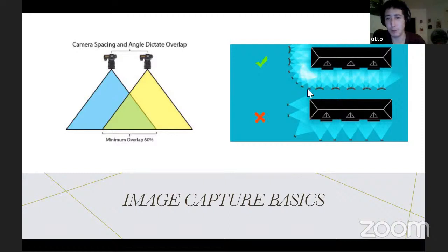And then you want to increase your overlap by basically double over a corner. And that's because corners are where the triangulation between the two faces can come apart. So it's important to have more overlap on your corners so the whole model is captured. Having just one image, as on the bottom here, is likely to cause problems because there aren't enough features detected on either side of the corner for each section to be joined to each other.